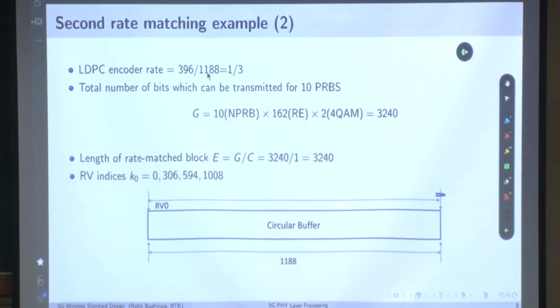Because you have generated fewer parity bits than what the user has asked for, you reread those bits. It's not retransmitting; you reread those bits and transmit them again in the same coded block. This is not hybrid ARQ, please keep in mind. This is only RV0. We run into this condition because you have generated a higher code rate than what the user has asked for. You have generated fewer parity bits than what the user has asked for.